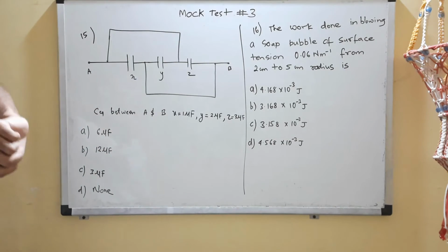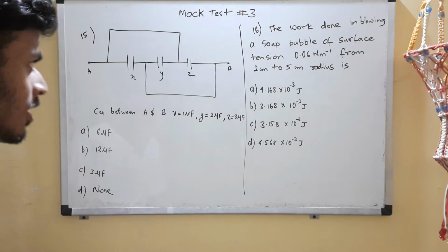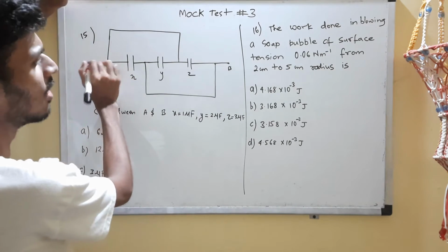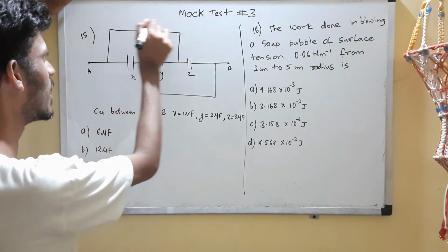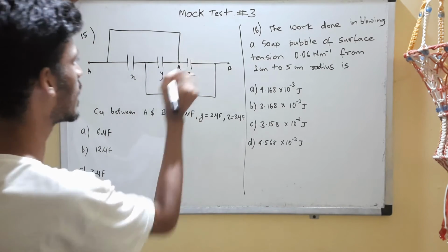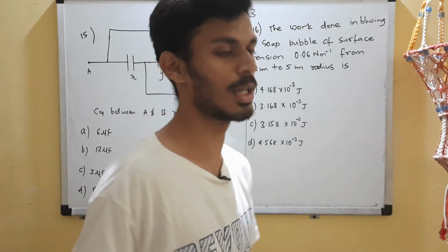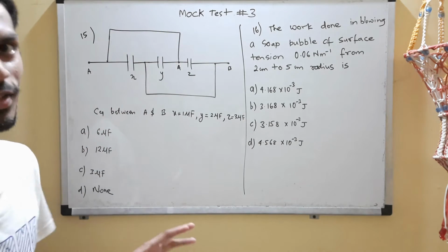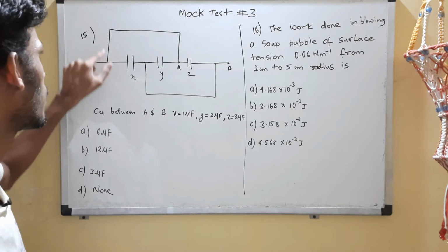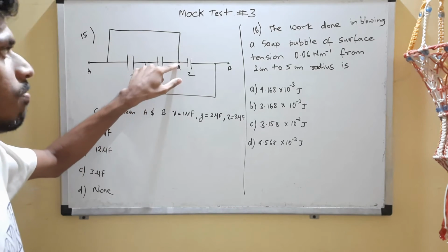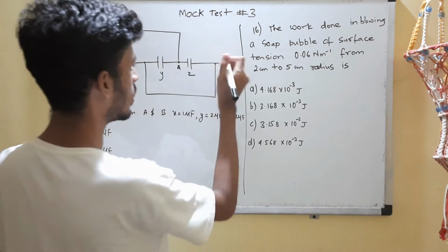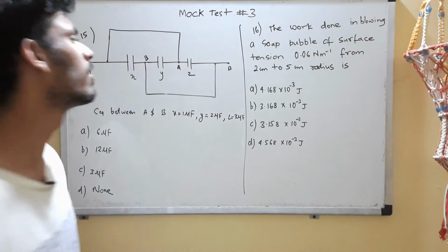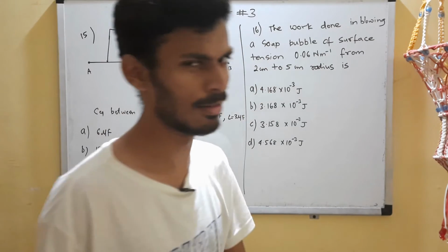First of all, you can't make out whether they are in series or parallel. So the concept over here is to look out for the potential. Let's assume the potential here to be A, so here also it will be A. As long as there is no element, resistor, capacitor, inductor or any other element across the conductor, the potential will not fall. So if the potential over here is A, here also, here also, here also it will be A. If here the potential is B, here also, till here it will be B. No potential falls across the wire basically.